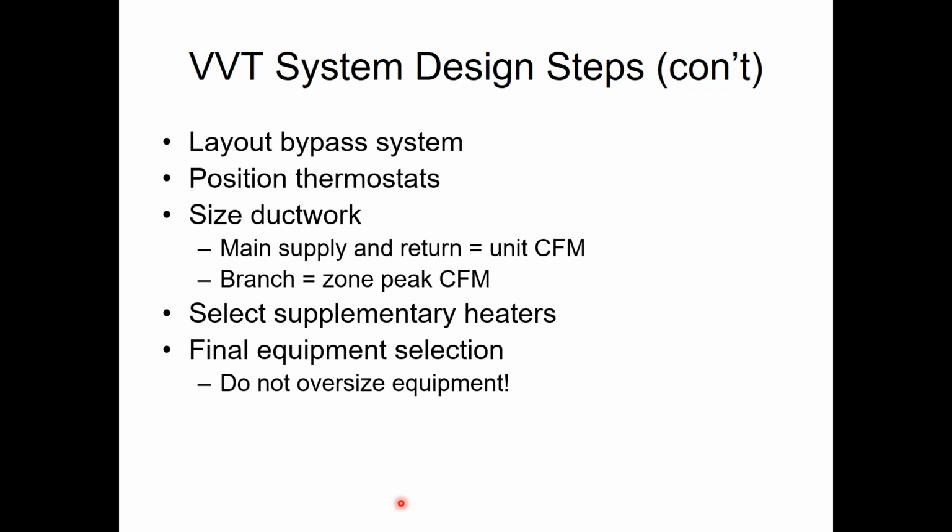I really, really hate it on zoning systems because not only is it oversized if I had all the dampers wide open, which is a problem, but I'm never going to have all the dampers wide open. So it's really a big penalty to me.